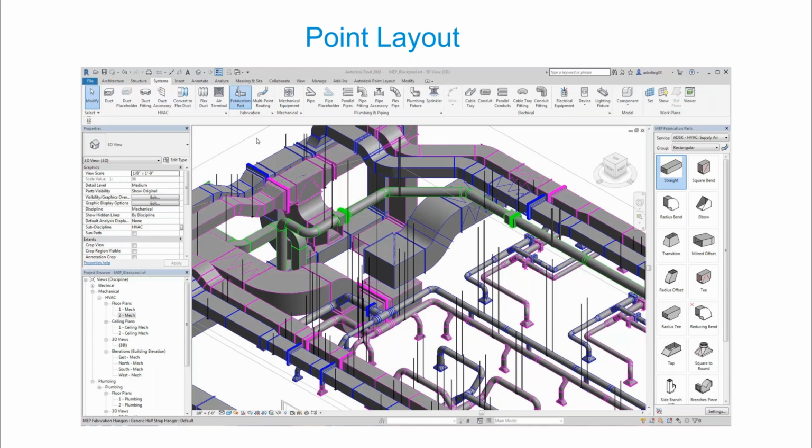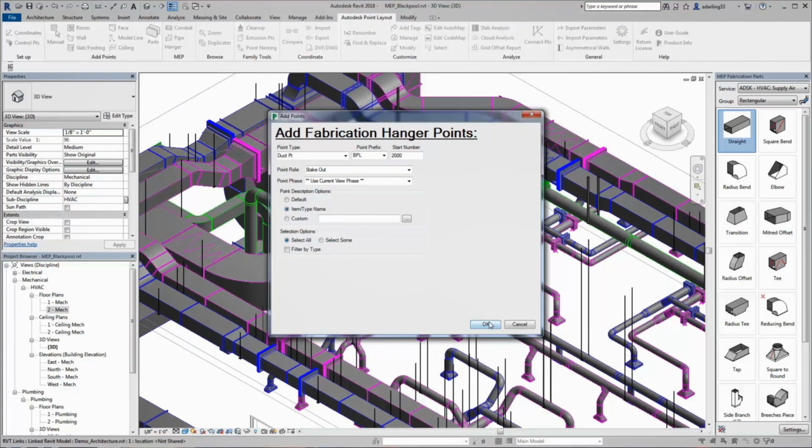So these are the complete point numbers. I'm applying it right here. Inside the Revit also you can get all the points. When I click on zoom, it takes me to the specific hanger which has that point, the easting, northing and elevation point. It takes me to that.